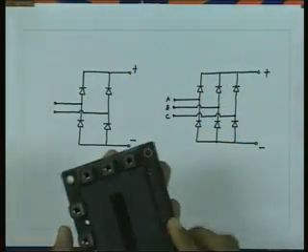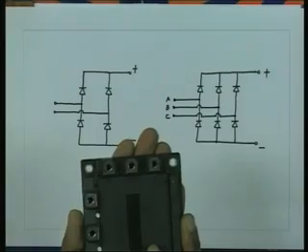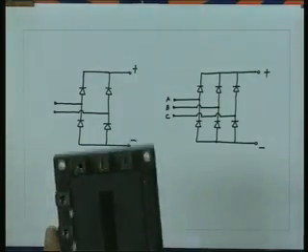So, therefore, the locus in the VI plane is not going to be along the x axis and along the y axis. There are limits. I had shown you there are 6 devices here, or 3 such legs, each of 75 ampere and 1200 volts it can block. But then each device at any given time will not be able to carry 75 amperes when the voltage across it is 1200 volts. No.